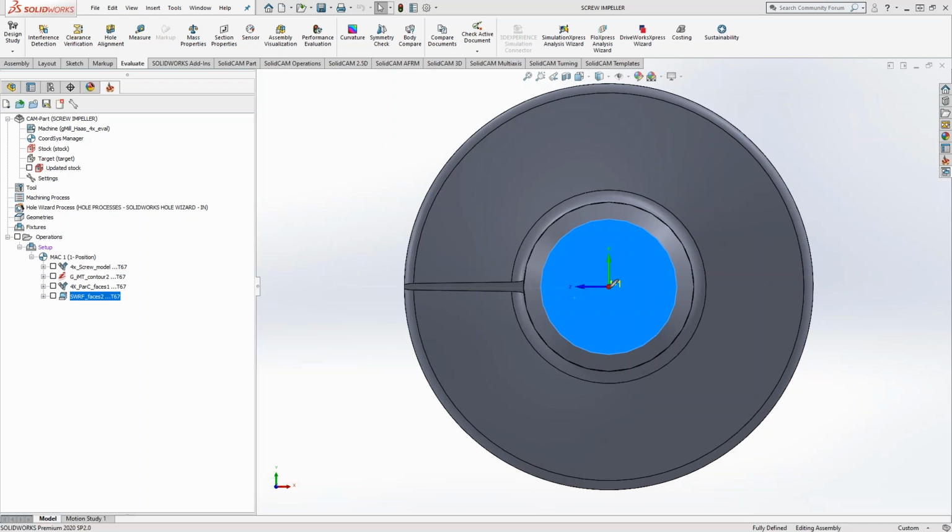Okay, so for wrap geometry, the tool is always pointing, if I draw a tool like that, the tool axis, the tool vector is always pointing towards the rotary in wrapped geometry. This is not simultaneous fourth axis. If it was, we would get the ability to wander in the radial direction. But because we're doing wrapped, the tool is pointing right at the rotary. So that gives us some limitations when we do wrapped geometry.